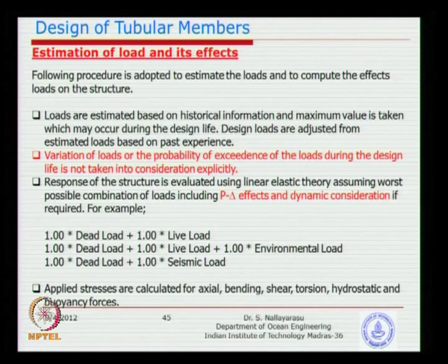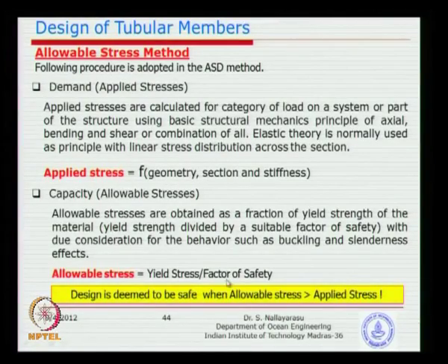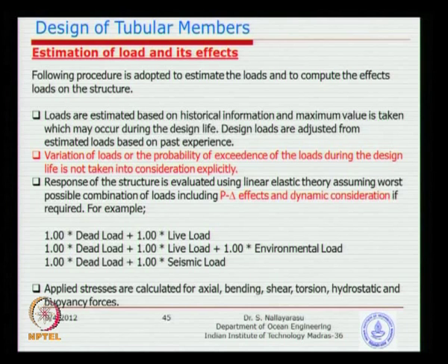We simply accumulate the loads to the maximum possible extent, because we have only one factor of safety which takes into account all the uncertainties that we have left behind. Whatever we have not investigated, we simply put in a bigger basket, and we give a factor of safety which will take care of everything, but what we do not know is whether that factor of safety is adequate or not. So, that is one of the drawbacks we have left behind, but so far I think it is doing well, since so many structures have been designed.